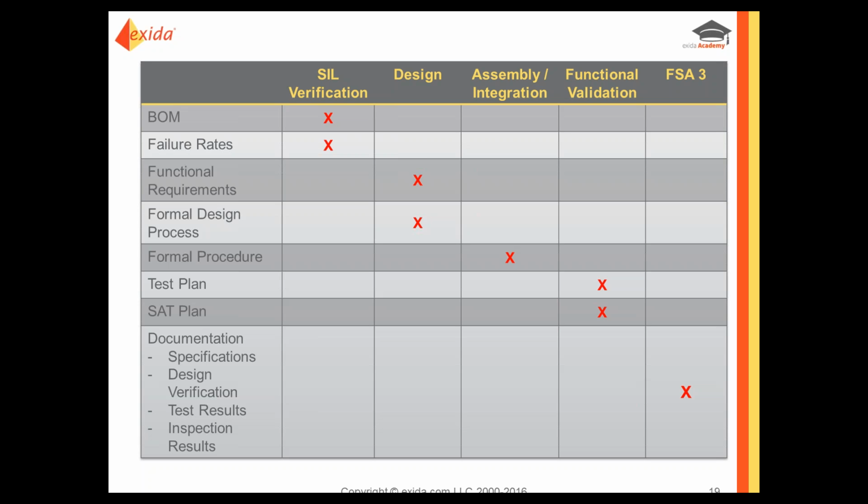Another question was what's covered by Functional Safety Assessment 3. That's essentially everything through system design, risk targeting, system design, and system implementation. You have to show evidence that that's all correct in the IEC 61511 life cycle. So it's the process hazard analysis and the design and implementation main phases, and there's lots of steps in there. That's the safety review that must be conducted prior to the hazard being present. So FSA 3 covers all of that.